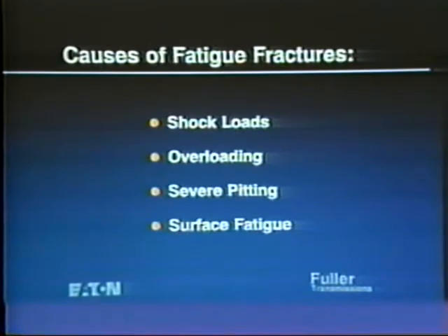Fatigue fractures are caused by extremely high stresses on a gear tooth over a period of time. Possible causes of such stresses could be shock loads causing a small crack in the tooth, an overload condition, severe pitting, or surface fatigue.